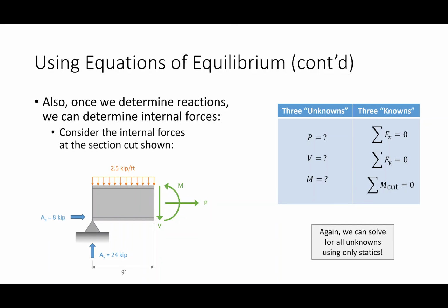One of the common tools that we're going to have at our disposal is the ability to cut a section. And that's why I say the secret weapon of structural engineering is a samurai sword or a lightsaber if you happen to be a sci-fi fan. But the truth is, if I have a beam and I just slice through it, I propose that inside that beam there are unknown forces as well. And it's those forces which, as a structural engineer, would help me figure out how big this beam needs to be. How wide do the flanges need to be? How thick does the web need to be in order to safely resist those loads, right?